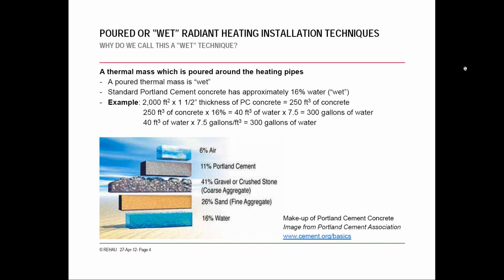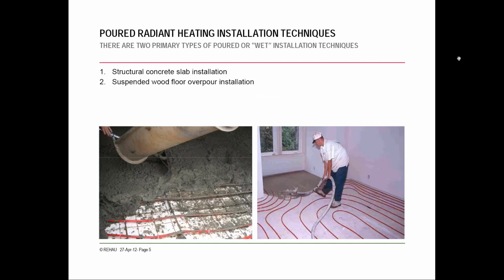In addition to a wet poured mass such as concrete, if you're using a paver system for a snow melt, for example, you may be installing the tube within the sand bed. It again will follow the same techniques that we're going to look at here. As I mentioned, structural concrete slab or an overpour installation are the two most common wet installations.